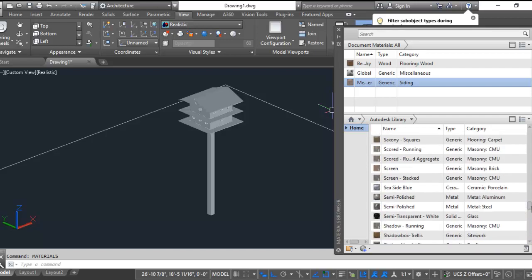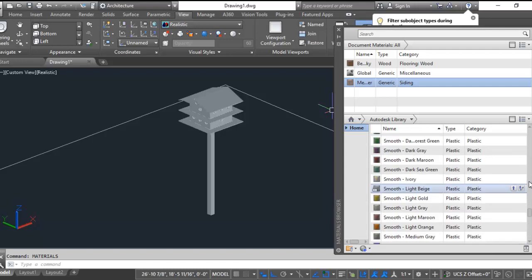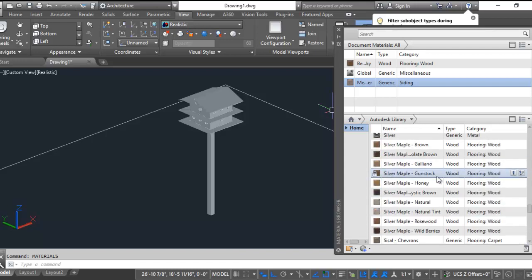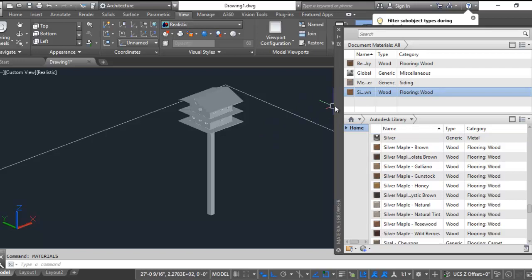And there's so many to pick from that you'll just kind of play around till you find something that looks appropriate. Do brown maple. Click the up arrow. Now that you have these, drag the little preview or the thumbnail to the material you want it applied to, and it will apply that.